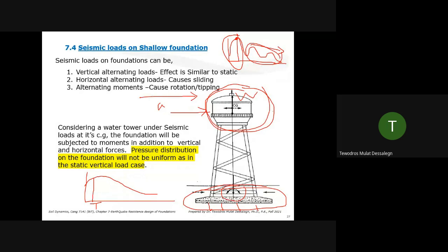If you do a time history analysis, the force is less, because multiplying it by 1.5 here and picking this peak value is very conservative. There is a penalty out of it. Your design would be a little bit uneconomical. More reinforcement needed, more sections needed. But it gives you a quick analysis.